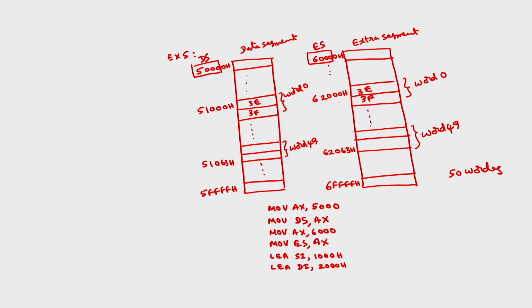In total, 50 words you have to compare. So, MOV CX, 50. What is the hexadecimal of 50? 50 is 16 times 3 is 48, plus 2, so 32H. 64 will be 100 bytes, and 32 hexadecimal is equivalent to 50 decimal.